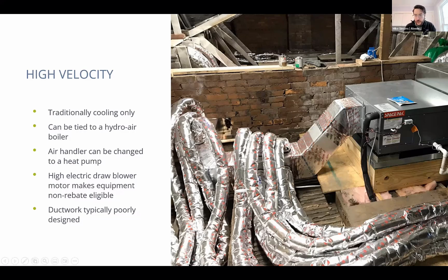But because we're trying to push air through this teeny tiny ductwork, it needs a really, really strong blower motor. The blower motor uses so much electricity that any measure we use, in terms of SEER or HSPF, to think about equipment efficiency, it misses those marks. So do know that a high velocity system could be tied to a great heat pump, but the blower motor uses so much electricity that it's not going to qualify for any rebates.